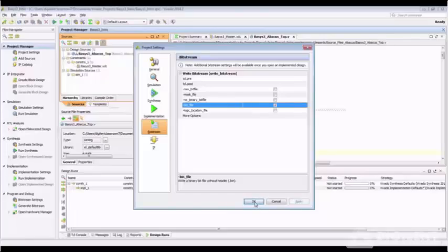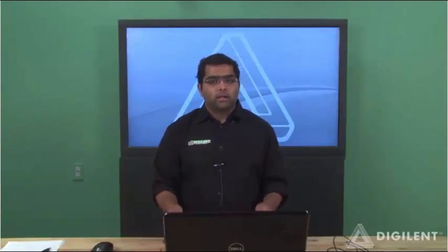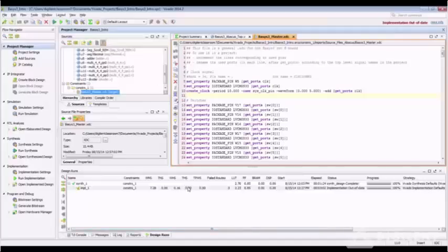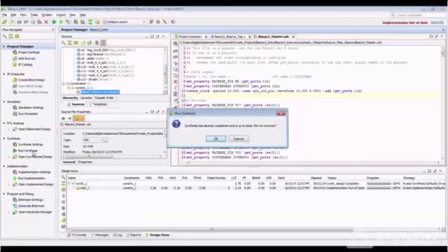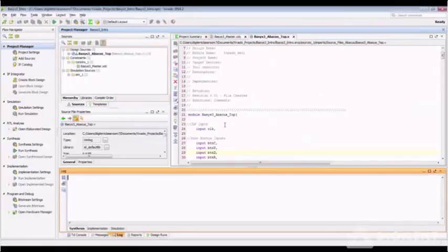And when you do that, once you power on your device, you can just directly run your project and you don't have to program the FPGA all the time. For this, let us set some device properties beforehand. To edit the device properties, this can be done in the Synthesis Design Open window or the Implementation Design Open window. So instead of generating the bit stream at one go, let us run the synthesis first. This will generate both the .bit file and the .bin file.